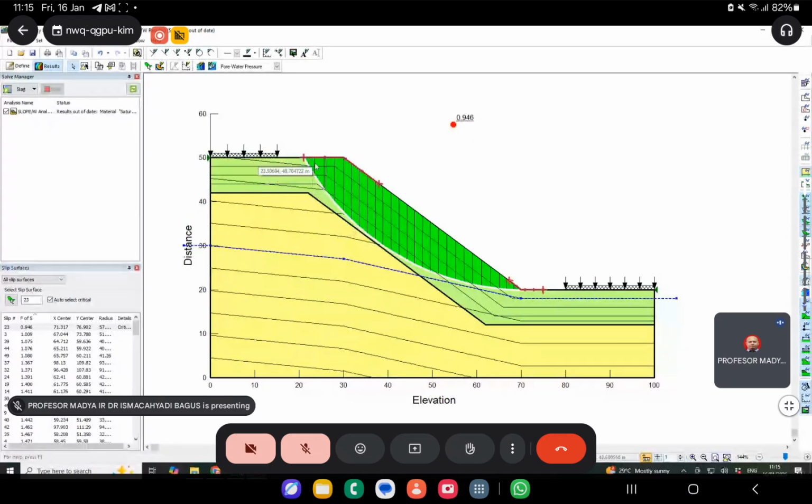So you only have the resisting factor of friction angle. That friction will resist the additional weight from your soil, and that is where the factor of safety reduces. This is based on FOS equals the resisting moment divided by the disturbing moment.